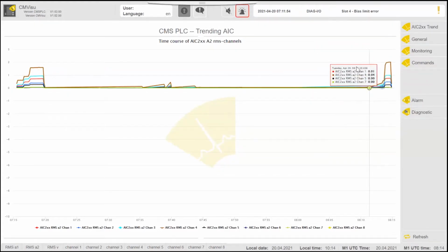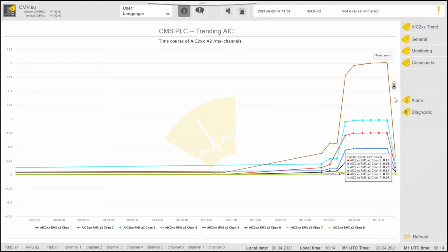But what we can also do during this measurement is we can take a more detailed measurement, which creates a waveform from the vibration of the machine, and that measurement can then be sent off either off ship to a specialist on shore, or if you have a specialist on the ship, somebody at the ship can take it away and look at it in a more detailed system.